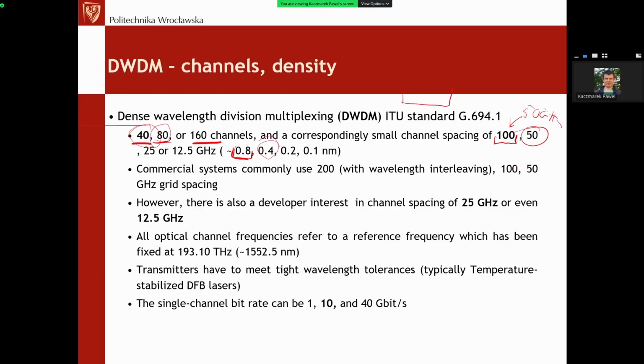So the system needs to be considered as a balance between the number of optical channels and the frequency of the modulation, or the bit rate of one single channel. For this 100 gigahertz spacing, 40 gigabits per second will be quite possible. In fact, it is dedicated to such systems. But if our optical channel spacing is smaller, we will start to have a limit on the maximum frequency we can modulate the signal with, to avoid crosstalk between the channels.